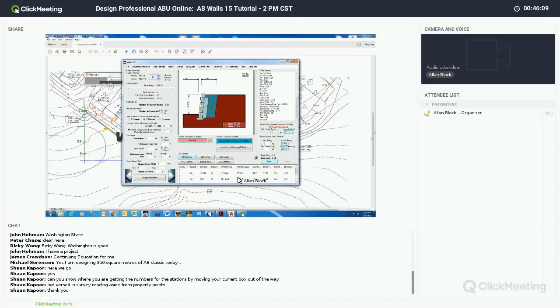In the spreadsheet below, we have all of our internal calculations, providing you all of your overstress, block pullout, and soil pullout safety factors. And then this is also the area where you have to make any changes if you need to. At this point, everything is above the minimum because nothing has yelled at us, and all of our cells are white with black text. If something were to fail, the corresponding cell to the corresponding safety factor would turn yellow and the text would turn red. So it would make it blatantly easy for you to find if something were to fail and you can fix it. All right.